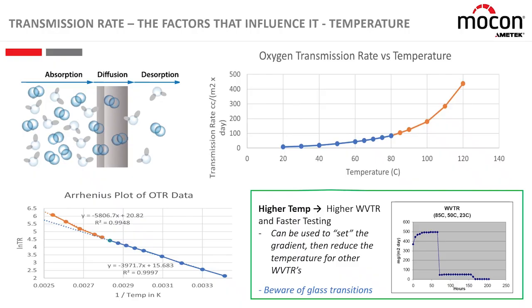But the speed at which they move through, that diffusion coefficient, is really tied to temperature. Temperature is energy, and with more energy in the system, the faster those molecules diffuse, the faster they wiggle. They just move quicker. So with increasing temperatures, I've got increasing energy, a higher diffusion coefficient, and then more water vapor transmits through my encapsulation material.